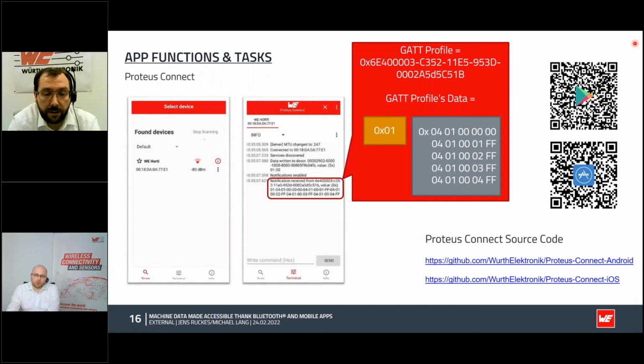In this case, this is an example of receiving the initial status of the LED control directly after connecting to it. We see in the yellow or orange marking the 1 byte overhead, which is hexadecimal 01, which indicates data, and then some sort of protocol is implemented. And spoiler alert, it looks like it's 5 channels, each with a PWM value. So that's what's happening here.